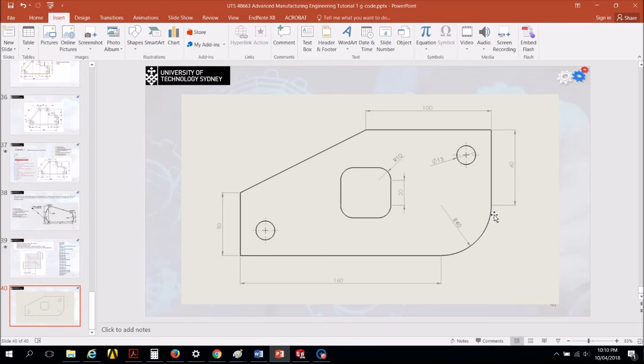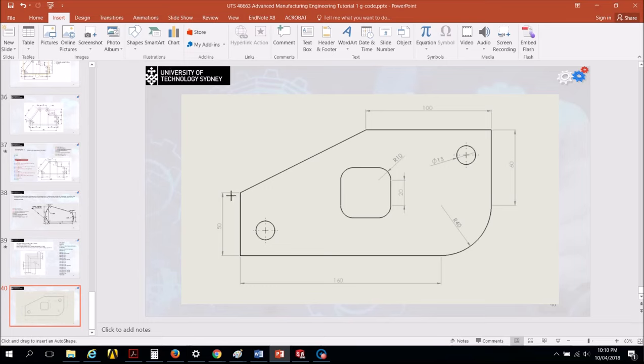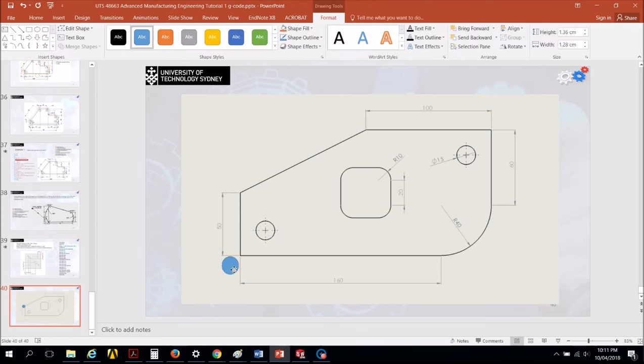Okay, now I would like to do the cutting for this shape. Once again, I'm going to consider the same process. I have the stock, and I have 1 millimeter left from each side before finishing this work. Now we have something called rough cutting, and we have finish cutting, and what we're going to talk about now is the finish cutting for the profile cutting. So I'm going to choose a cutting tool. It's going to be a circular cutting tool with any diameter I choose. Now consider that this one is going to be 10 millimeter diameter. This will be my first position.